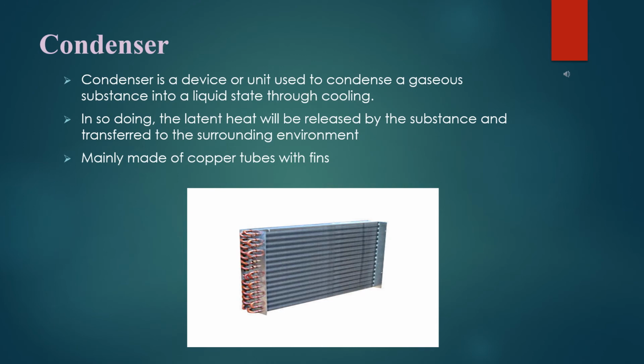Condenser. Condenser is a device used to condense a gaseous substance into liquid state through cooling. In so doing, the latent heat will be released by the substance and transferred to the surrounding environment. They are mainly made of copper tubes with fins.